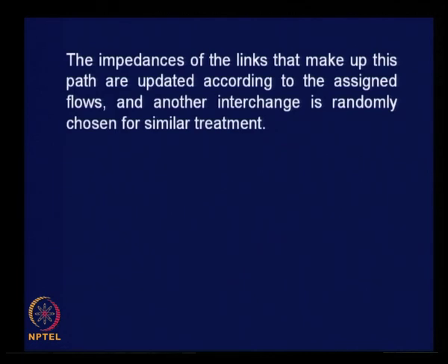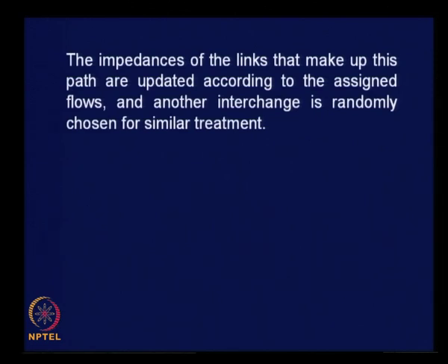We take one pair of traffic zones, right, and assign traffic from one zone to another. After identifying the minimum path tree, a set of links will be loaded with some traffic. For subsequent assignment on the same link, when we consider some other zonal pair, we need to know what will be the exact travel time. It will not be equal to the free flow travel time because we already have some traffic assigned on these links, is it not?